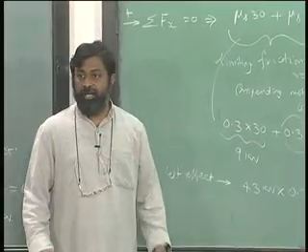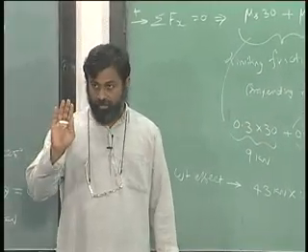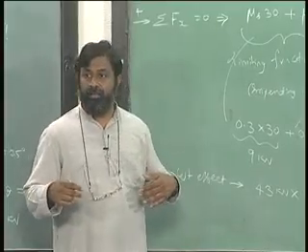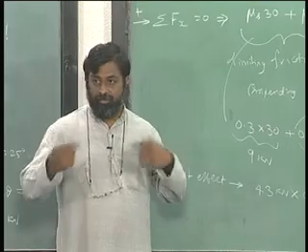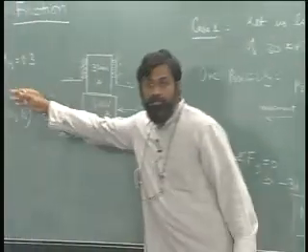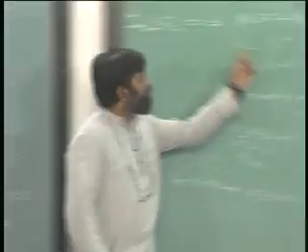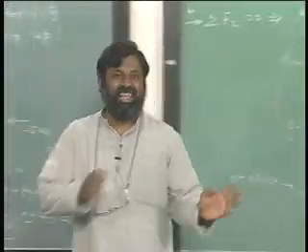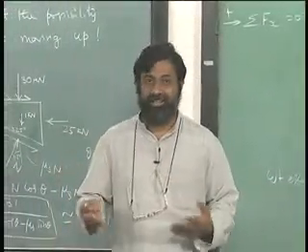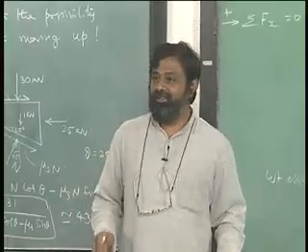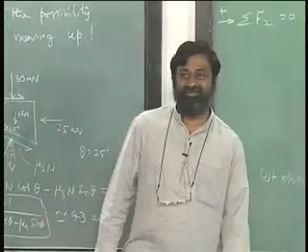If I have to think of a resistance, for example if I have to push this all the way like this, the resistance will come from this and the weight effect. So, I have to offset 18 plus roughly 18 again, or let us say 20 plus 20, so I need at least 40 kilonewtons to push this.